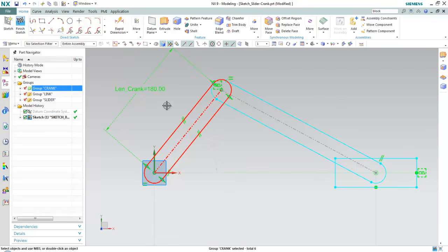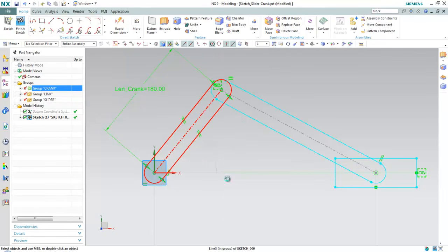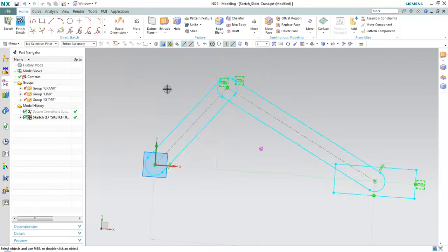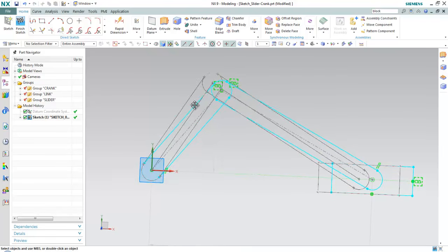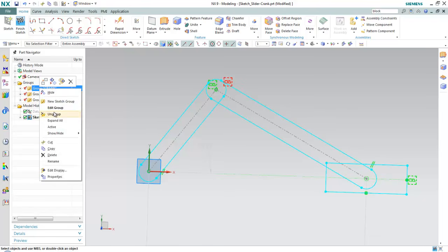if components or groups are enabled for the operation. So this is part of a group. See how it grabbed all that geometry? Then I can right click and turn off the active. See how the dimension's gone, but I did increase the length. So this is really just grouping geometry together, whether they have constraints or not, and having them behave as one entity. How you create this: if I come up here and ungroup this,